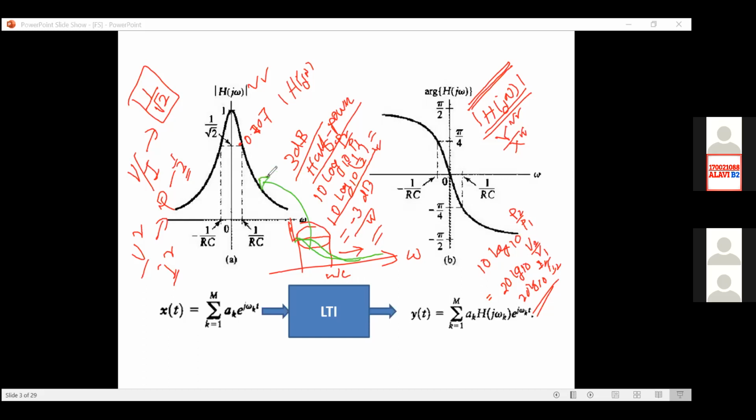Yes, sir. In order to define this cutoff frequency, you know that it cannot be determined exactly because your curve is gradually going down. So someone can define your cutoff frequency here, another can define it there. For this reason, we use some standard for defining the cutoff frequency, and the general standard is the 3 dB point. That means you consider your output usable if it is going down to half of its power. If your power falls beyond that, we will not consider that output a reasonable output. But this is a very restrictive definition of cutoff frequency.